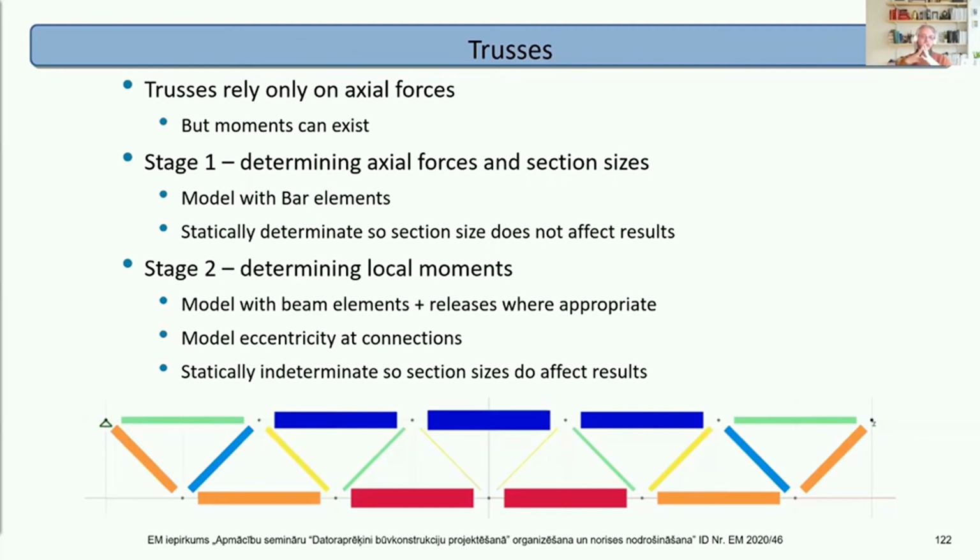So that's where I might start from, but later on you will know the forces, you will know the reinforcement, and so on. Also, of course, with computers, you can iterate. You can do an initial calculation, initial assumption, work out the reinforcements, reanalyze, recheck, and it can just bounce back and forwards between the various algorithms until they both give the same answer, and that's fine. Hand calculations, nightmare. Computer calculations, computers just love doing number crunching, just doing the sums until they're told to stop.